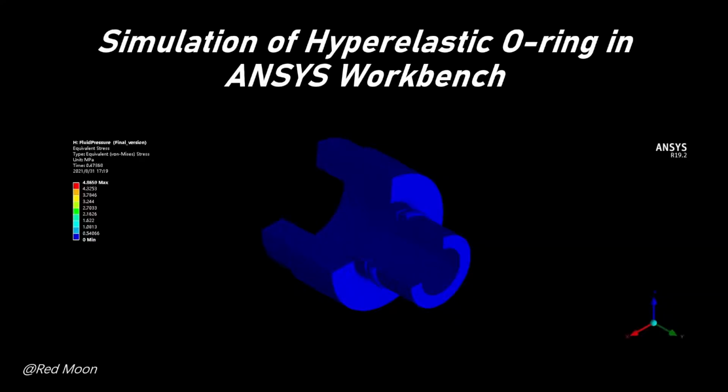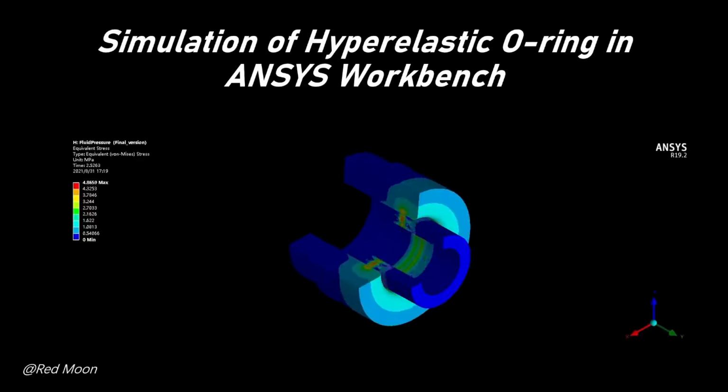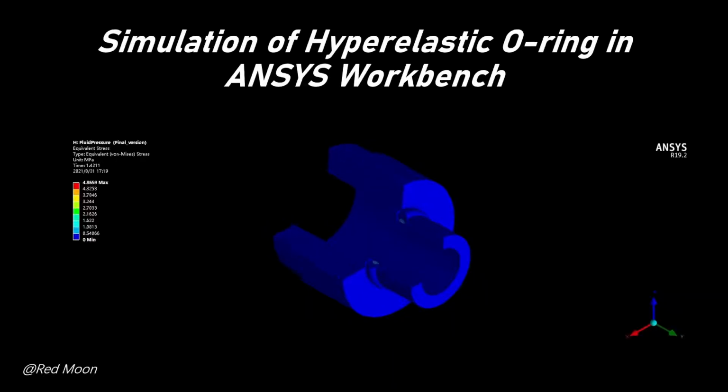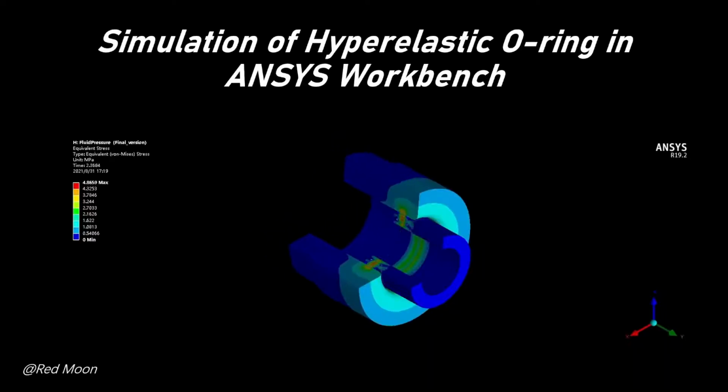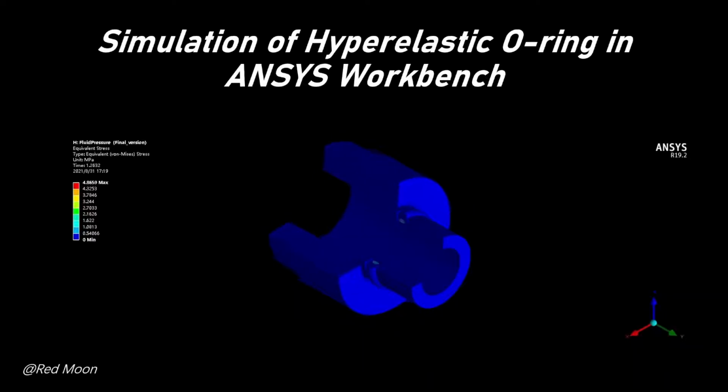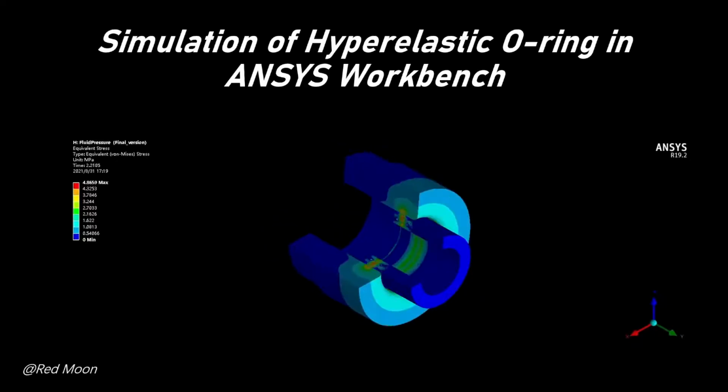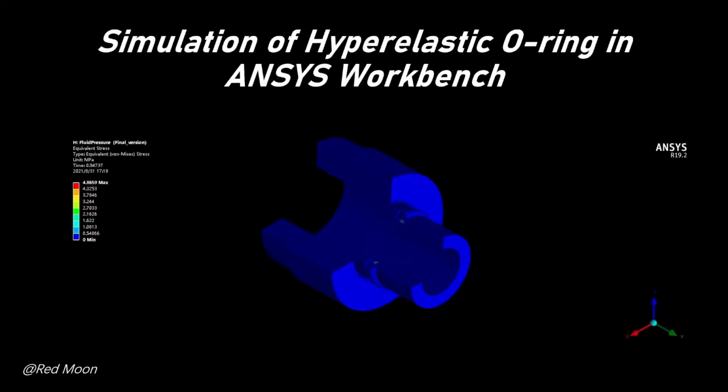The O-ring is a perfect industrial product, which is simple and useful. It's commonly used in piston seals to prevent fluid bypass between the piston head and cylinder bore while a hydraulic or pneumatic cylinder is operating under various operating conditions.